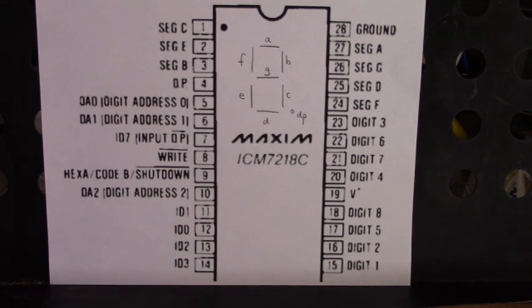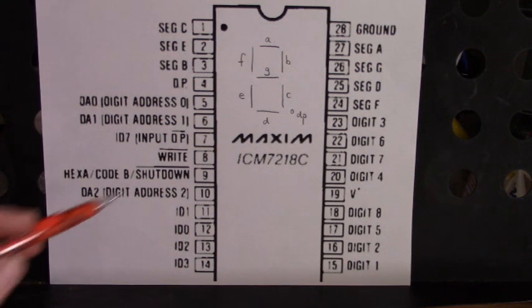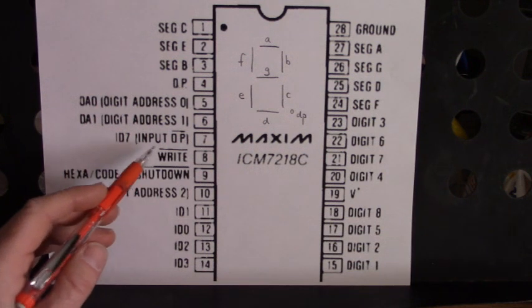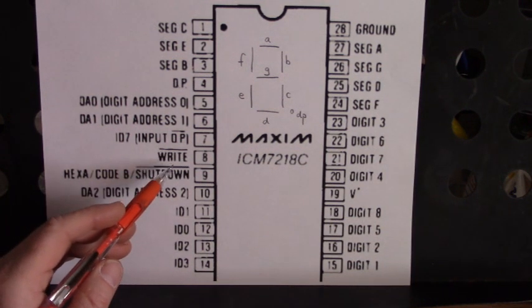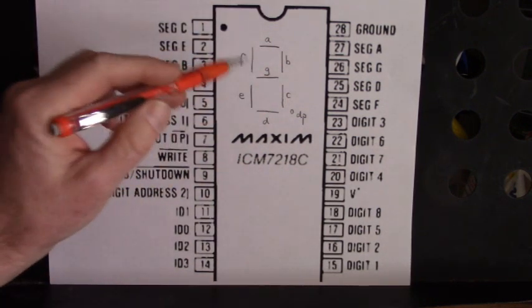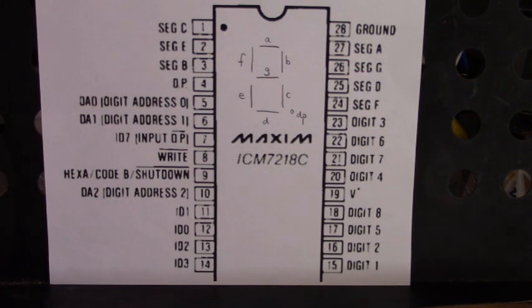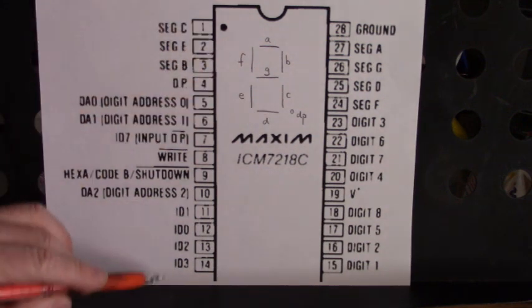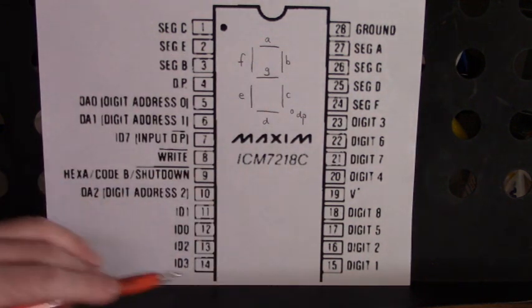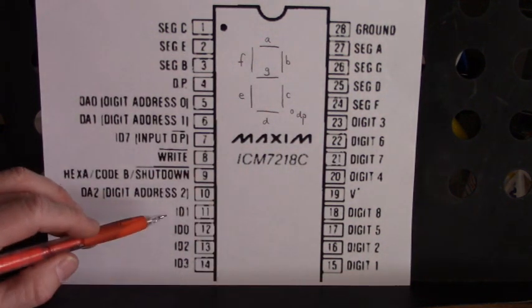Let's look at the characters. Oh, I'm getting sidetracked here. In order to do so, we have to drive pin 8 from a high of 5 volts, low and then back high. And that character would be displayed on that 7-segment display. Now let's look at the chart that determines the character that we display on the selected 7-segment display based upon the input data.